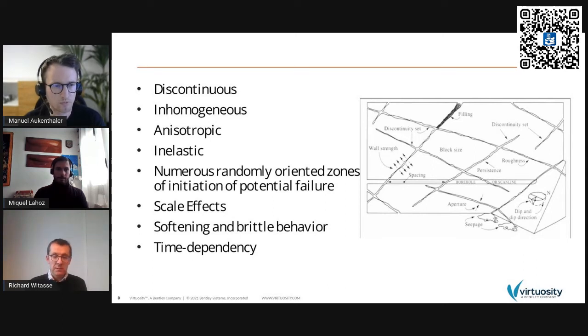So we do have here as well specific models that take this into account, and especially consequences about what we call regularization techniques. As once introducing a model or a constitutive model with softening, we may have mesh-dependent results, and specific techniques need to be used to take this into consideration and obtain mesh-independent solutions.